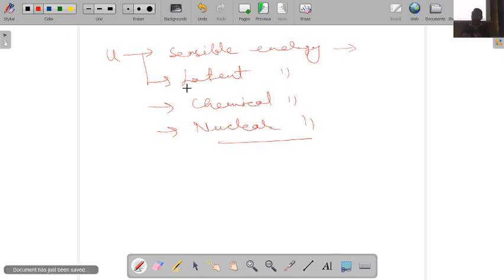Whenever you are giving energy, say you have reached 1 atmospheric pressure and 100 degrees Celsius, so you reached the saturation limit. After that point, if you add energy, then what will happen? Molecular distances will increase. It means you are breaking the potential of the molecules. So you can say that intermolecular potential is coming over here, because within a molecule changes are not taking place.